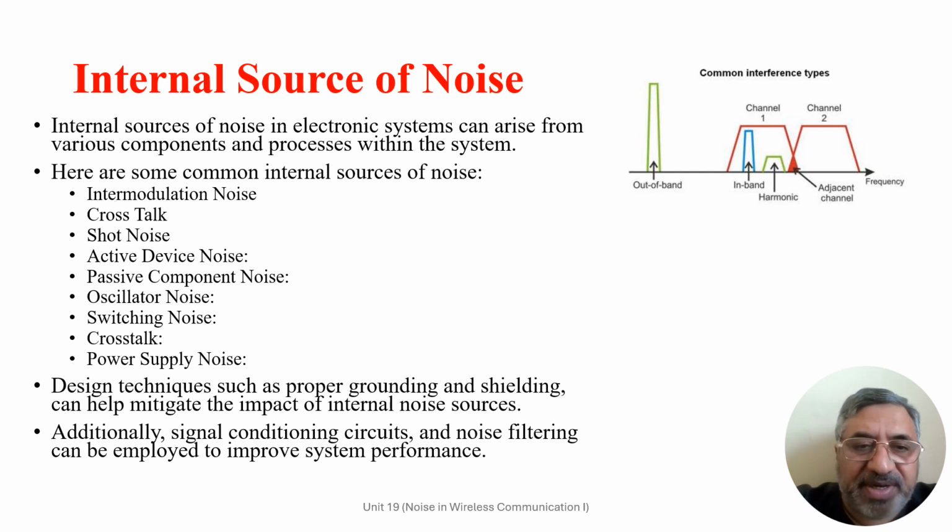Design techniques such as proper grounding and shielding, decoupling capacitors, low noise component selection, and layout optimization can control the impact of internal noise sources. Additionally, signal conditioning circuits, filtering, and noise reduction algorithms can be applied to improve the overall system performance.